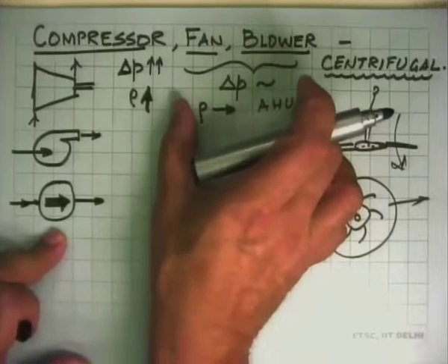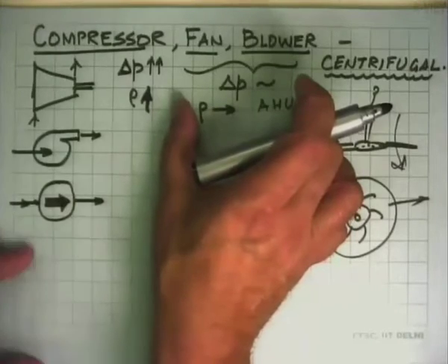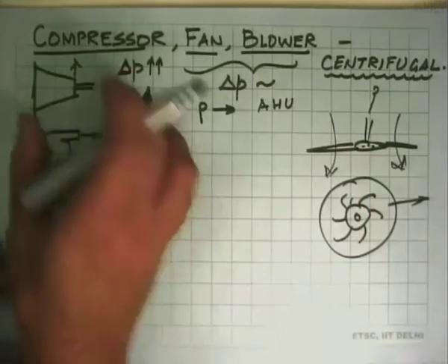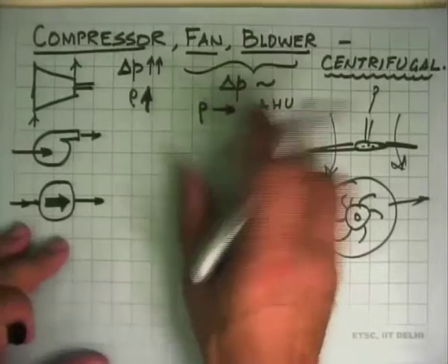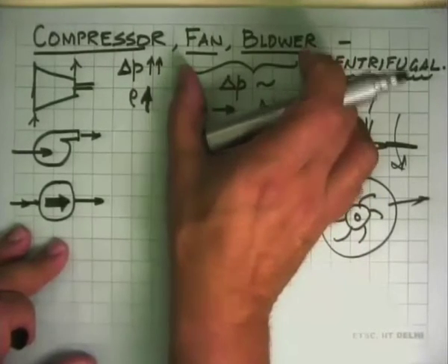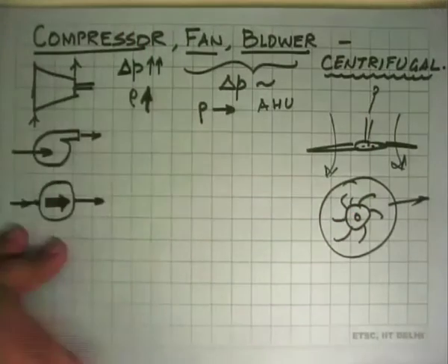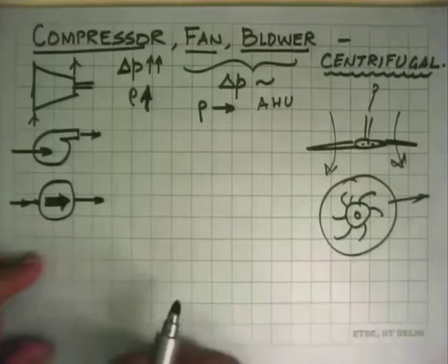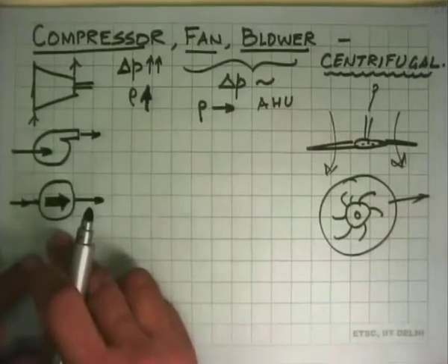So we can treat that air density is not changing even though it is air and small changes in pressure are there. But here we cannot make that assumption. And the reason we say that density is constant is because delta P is very small. That's why we can say the constant density or incompressible flows, this would be treated as a compressible flow with pressure changes.